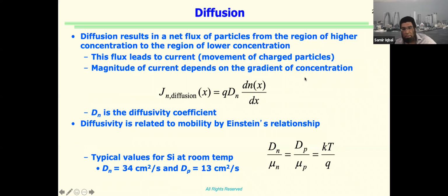All right, so the other part, diffusion. We haven't gone through diffusion a whole lot, but the relationship for diffusion is also straightforward. There are 3 parts to it. One is the charge concentration, the charge itself, Q. The other thing is diffusion coefficient, which is a constant, the diffusivity constant or diffusion coefficient. And how much is the change in concentration over the distance across which we want to find the diffusion current. So 3 parts to it: fundamental electronic charge, diffusivity constant, and the rate of change of concentration across the length on which we want to find the diffusion current itself, right?